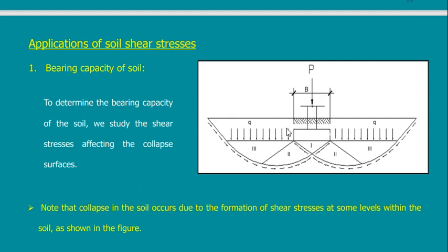If I have a footing here, and I have a load on top of it, what will happen to this footing? This footing will push the ground below. So I can divide the soil into a few zones. Each zone has a specific behavior. The triangle below is completely compressed by the footing. So this triangle will move down.